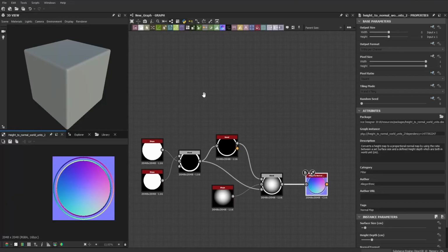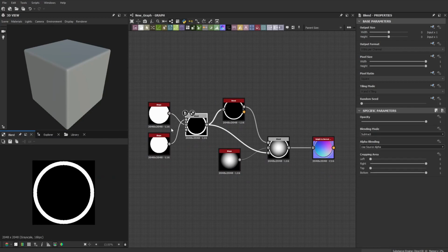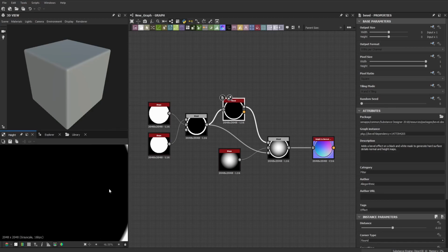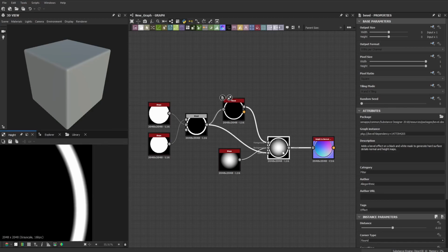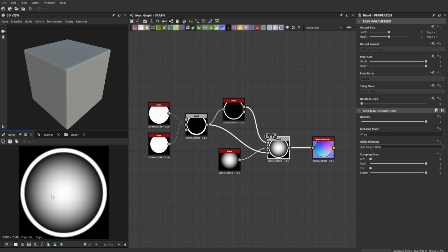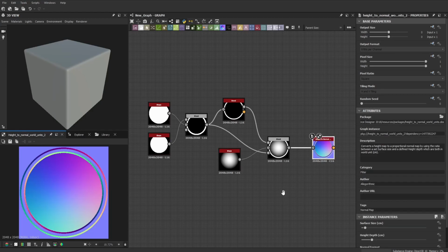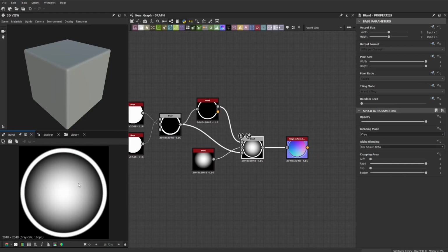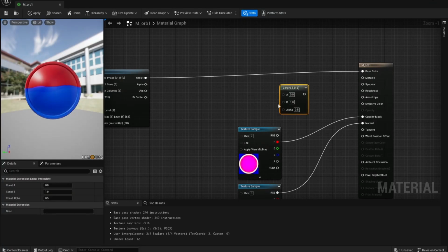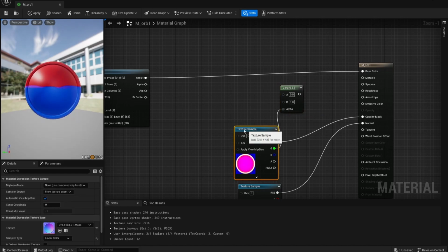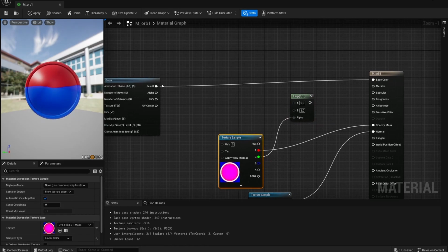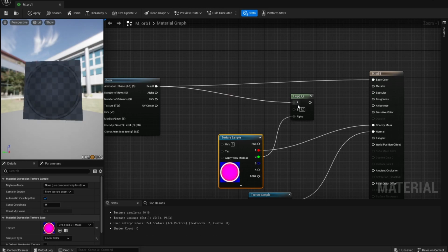Like I mentioned, in Substance Designer I made this basic graph. I basically took two spheres and made a ring out of this. Then I did a small bevel of that ring, and I combined it together with another shape here. So we have a shape like this, and then I get the normal map from that. Again, I stored this as an additional texture as a mask, so I can mask out the ring and the other elements. For example, I know that my green channel is the ring, so I can do something like this.